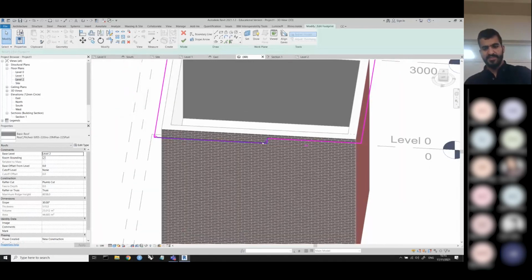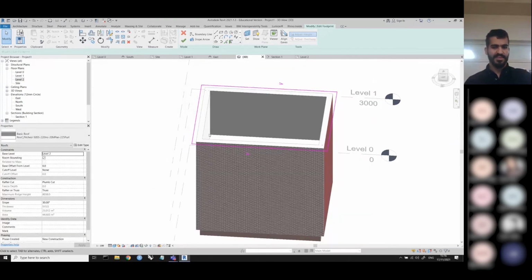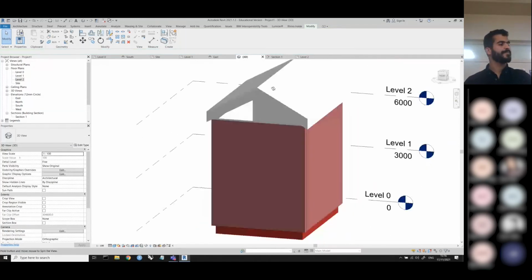Yeah, but I don't want to do these for now. I'm just going to go with something simple. So TR is a useful command to just connect two lines together rather than redrawing them. And then, of course, your delete button. I'll have these two sloped, and the rest I'll leave as is. So I'm just going to do this.